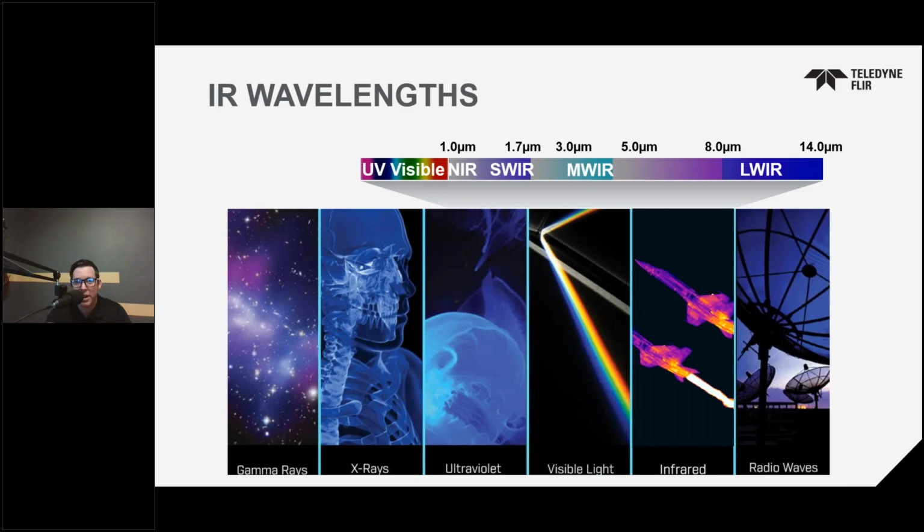Next is going to be midwave, MWIR. This is the standard range when it comes to most radiometry and high performance thermography applications. The slope of the Planck curve here is going to enable excellent contrast. If you recall, it's got a nice vertical aspect to it there. The detectors are exceptionally sensitive, typically better than 20 millikelvin. That's 0.02 Celsius sensitivity. And for many applications, there's enough energy to adequately fill the detector wells to run at very fast frame rates.